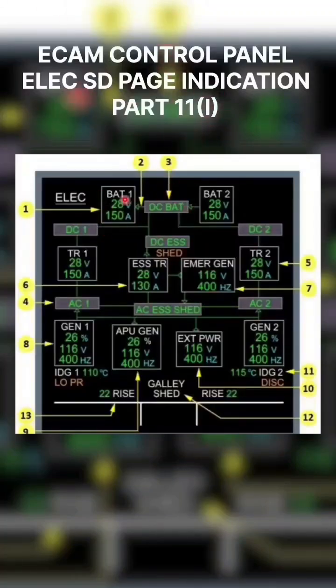If you talk about this, we will not go in there. There is a lot of concept, but this is the battery charger, the charge and discharge indication. Whatever you can see right now means the battery contactor is closed and the battery charging current is more than 1 ampere. That's why it's in green color.